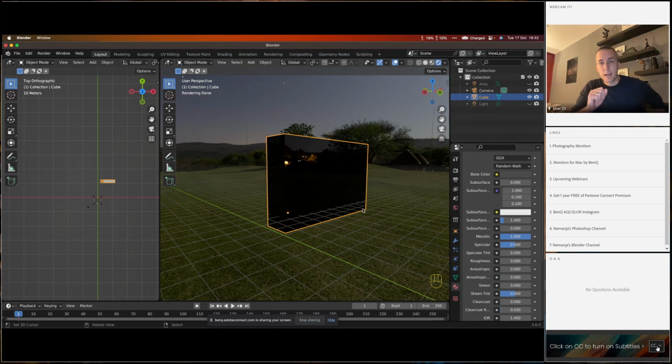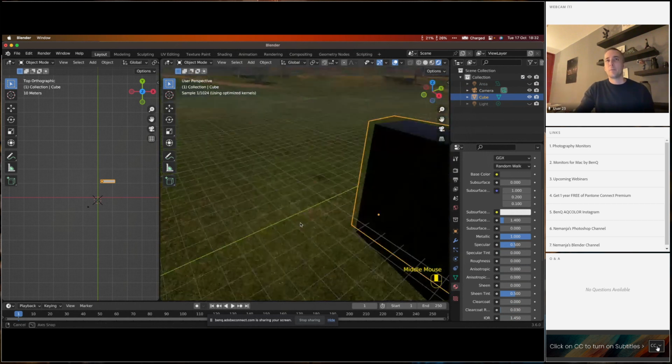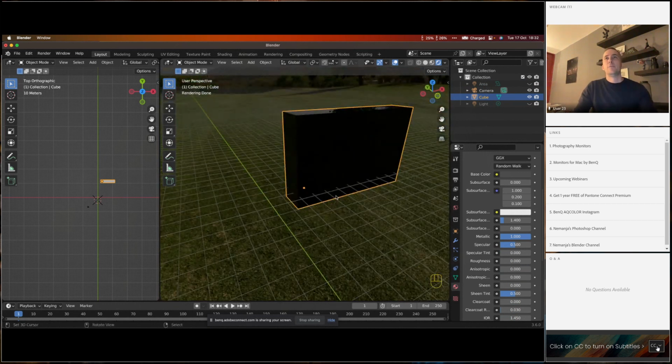Or you can make your own HDRI lights with a camera. There are a lot of tutorials online on how you can do it. It's a little bit complex technique with the camera, but if you have a 360 camera, then it's really easy. You just place the 360 camera on the spot where you want to put your 3D model, and then take several exposures and make an HDR, high dynamic range, photo, merge them together in Photoshop, and put it in Blender, and you have a spherical type of light. This is what I did with my model.